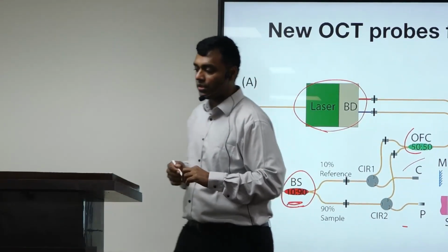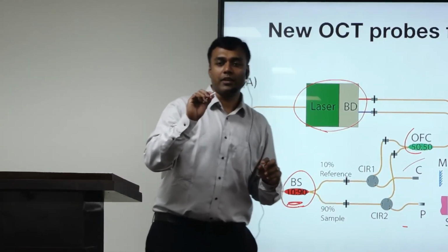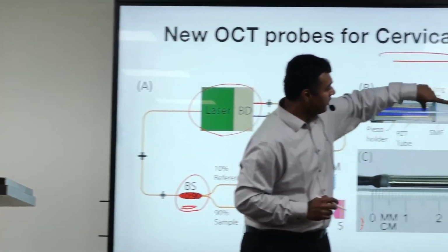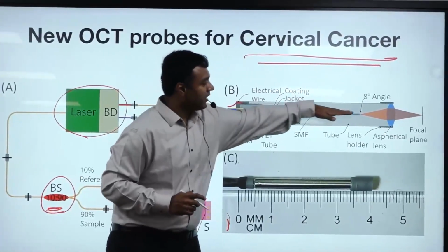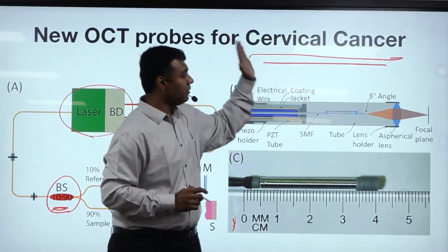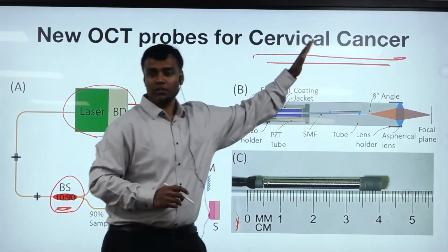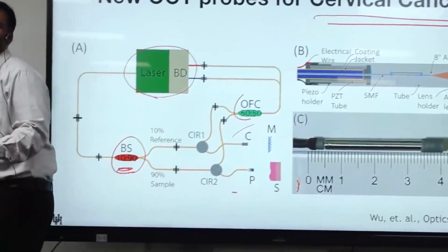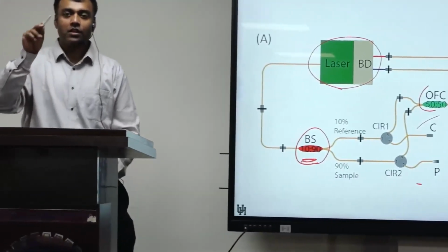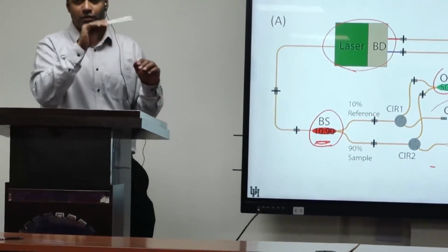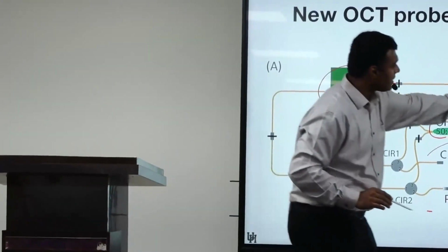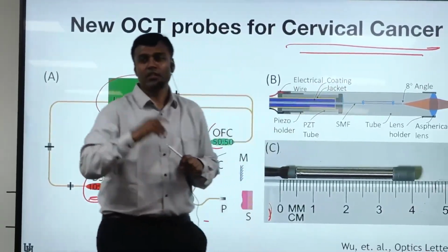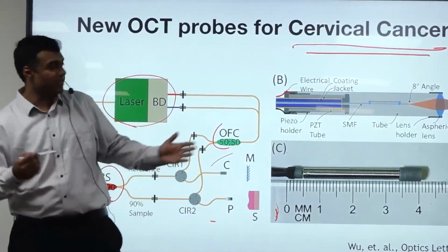One of the solutions is you can use the cantilever effect. Basically if you make a small deflection, and you have a long fiber here, this moves a little bit, this moves a lot, right? So you can use some kind of deflection mechanism which amplifies your deflection. Imagine this is fixed, this is moving, this moves a little bit, this moves a lot more, right? So there is an amplification to some extent, but that's still small.